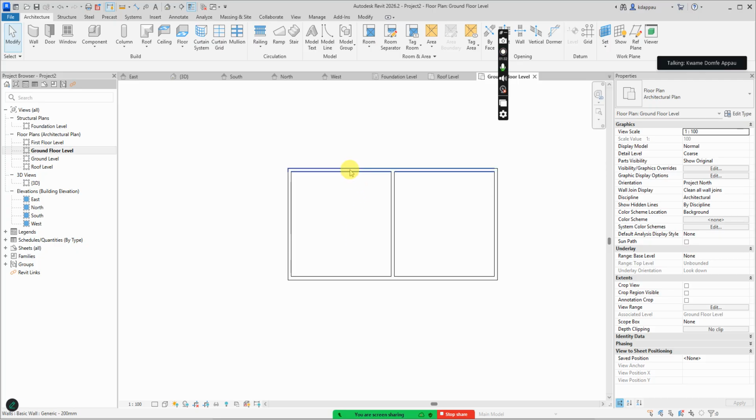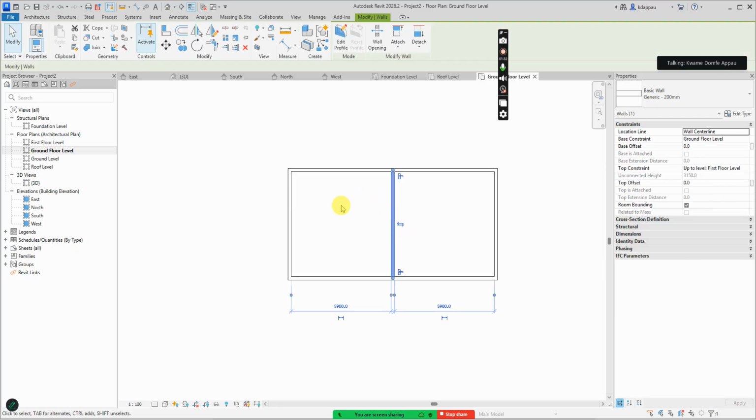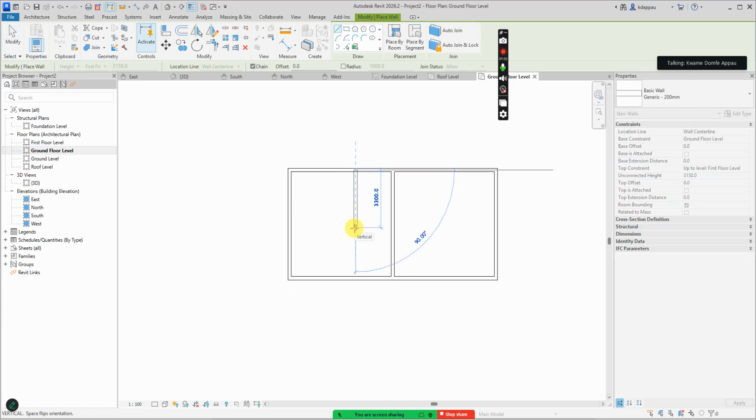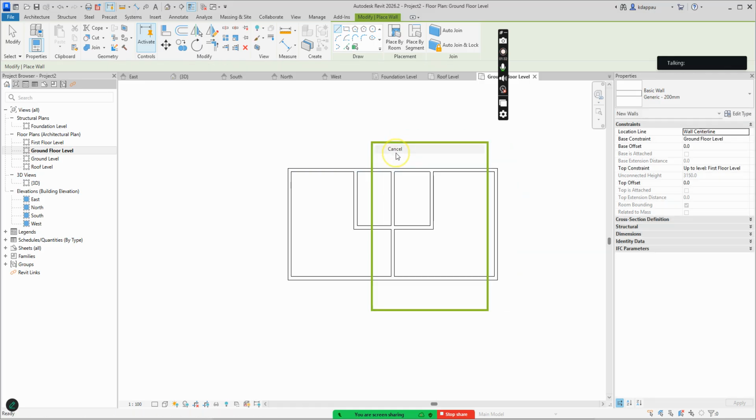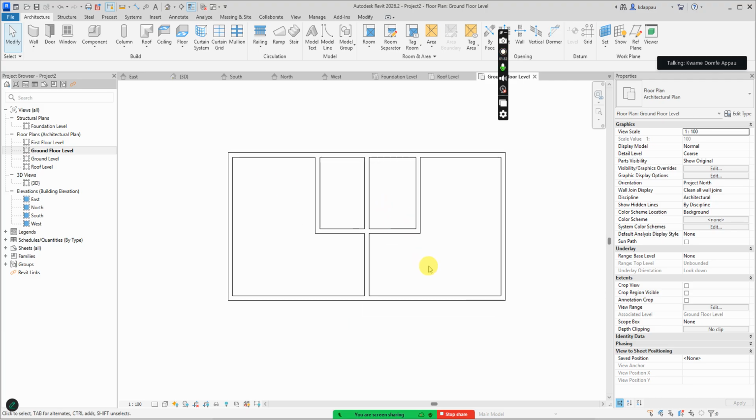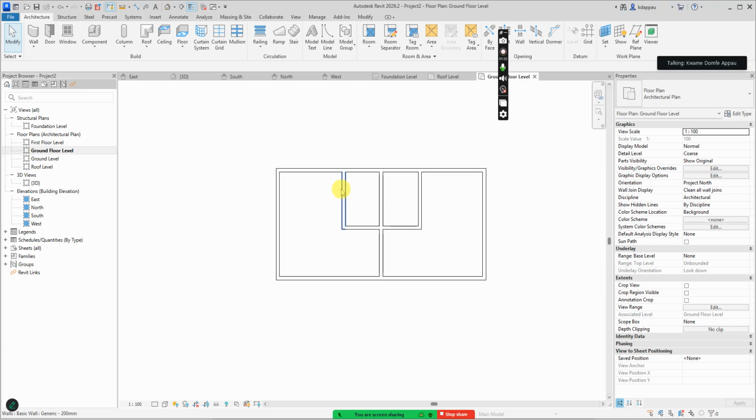If I want to partition this room further, I can come in here, create similar, and then start from here, draw another wall here, bring another wall here, then bring another wall here. And then I will decide whether this room is going to be a room or a shower or a closet or whatever. The discretion is based upon you.